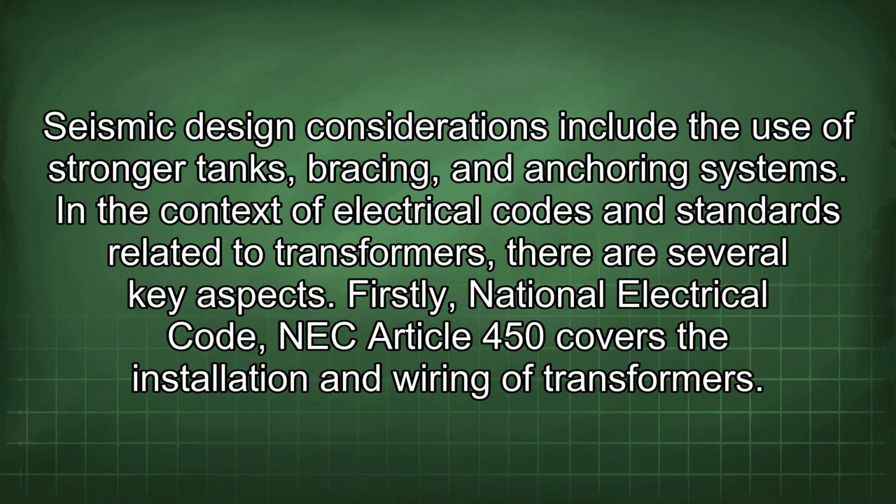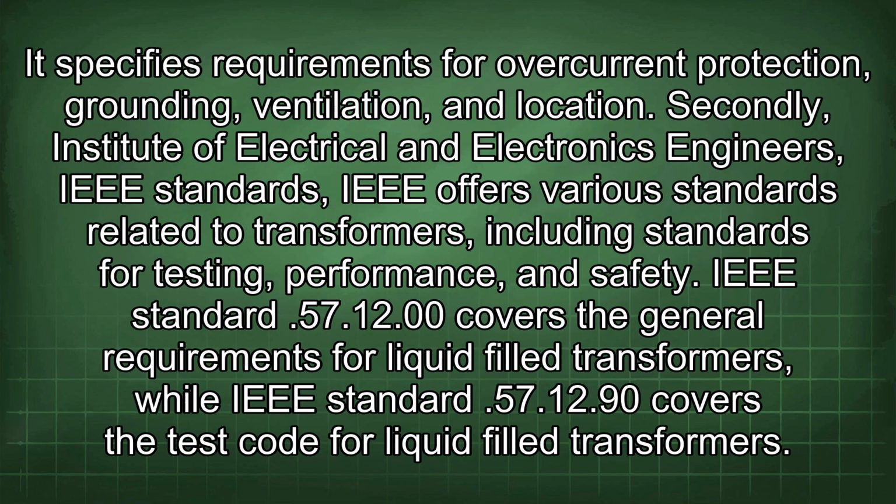In the context of electrical codes and standards related to transformers, there are several key aspects. Firstly, National Electrical Code, NEC Article 450 covers the installation and wiring of transformers. It specifies requirements for overcurrent protection, grounding, ventilation, and location.